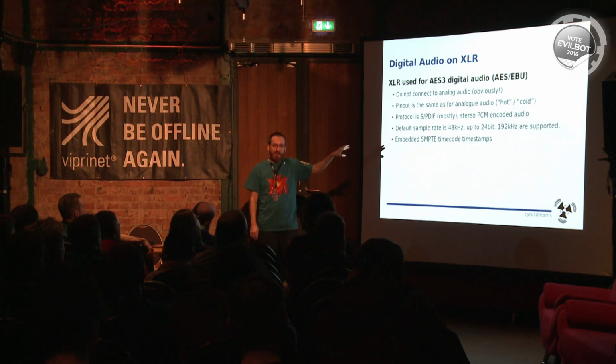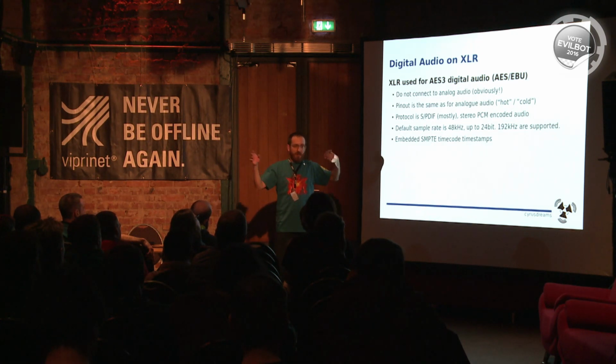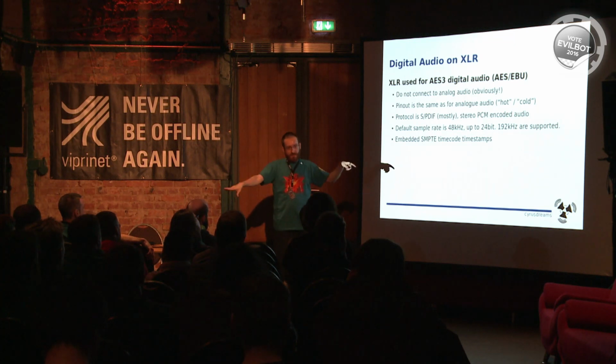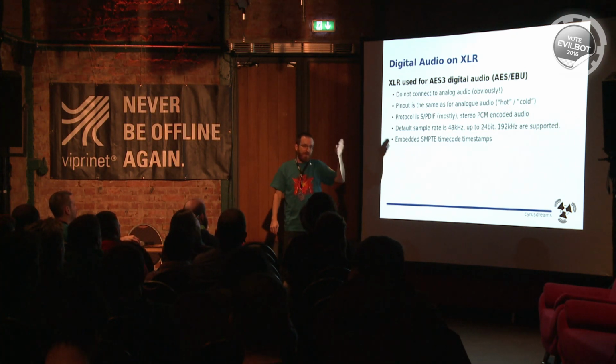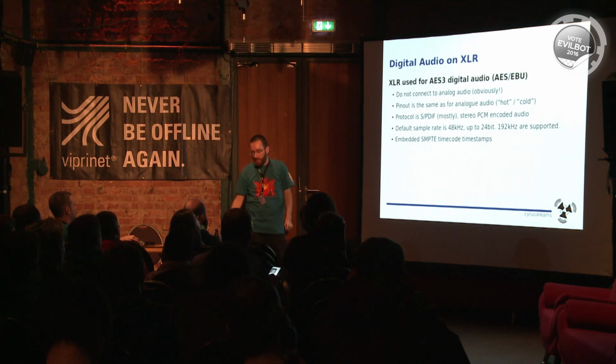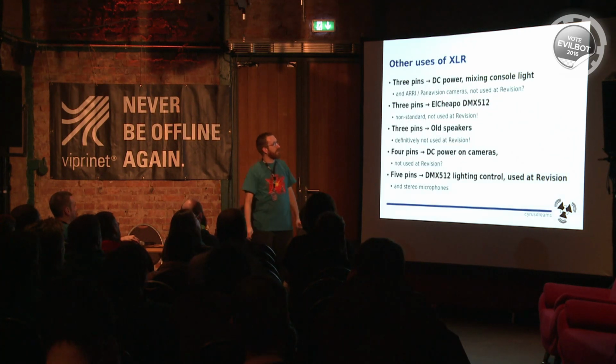Timestamps are very neat. If you have a video and parallel to that you have an audio recording, then you hook up a BNC line, a coaxial line, we'll see that later, where the timestamps are exchanged, and you can record the audio signal with the exact millisecond correct time frame, and it will just match in your post-processing software.